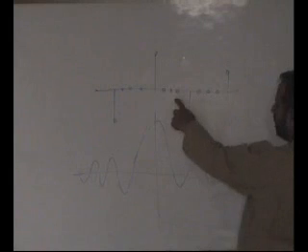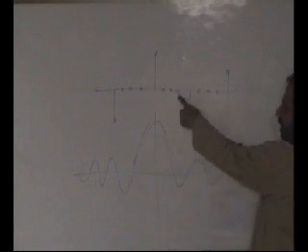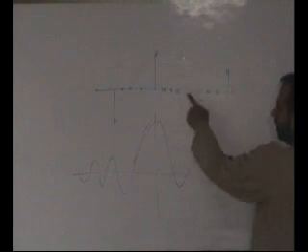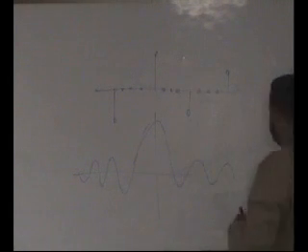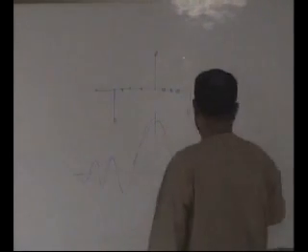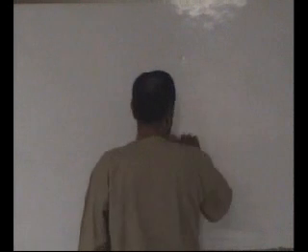Because if you do this, the filter needs to operate at a very high rate, at the newer sampling rate, though mostly you are multiplying by zero. So this is the motivation of polyphase filters: somehow you figure out a way to run the interpolation and decimation filter at a slower rate.